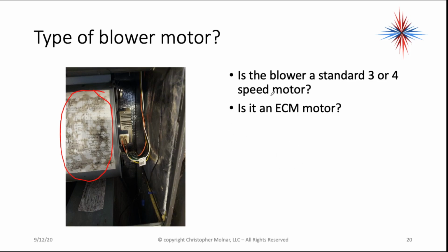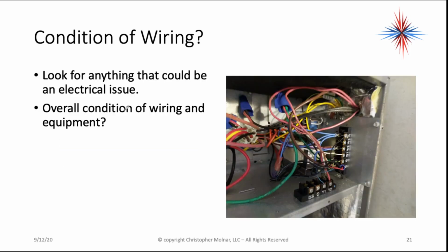ECM motors matter. Okay, they self-regulate for airflow. A lot of them are designed for specific static pressure, specific amperages, and they will self-regulate. Okay, we're still going to verify this, but overall, ECM motors do adjust for bad ductwork and bad filters.